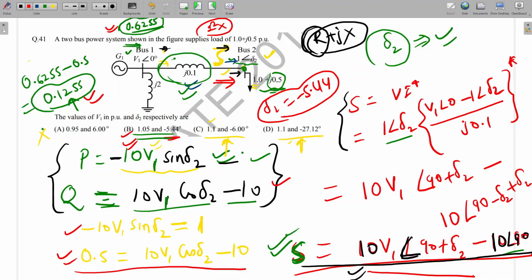But sir, from the sending end we have one element also connected, J2. See, after this bus we are looking. J2 will also draw some power, but there is no need to take care of this because it is isolated from our main circuit. Here J2 will draw a reactive power of V1 square by 2. That is a different thing and is not included in the question.